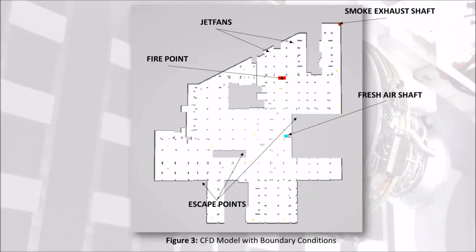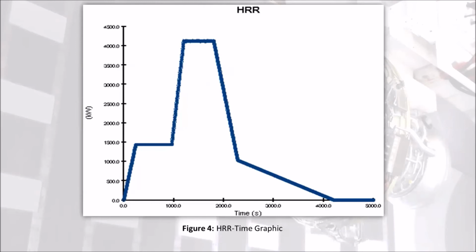Actually, in our mesh modeling, the area of the simulation model car park is divided into several small cells. The method used by CFD and FDS software is to calculate air temperature, velocity, optical density, smoke, and fire emission for each small cell.